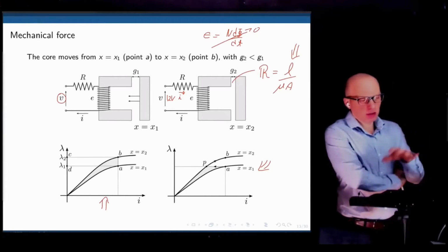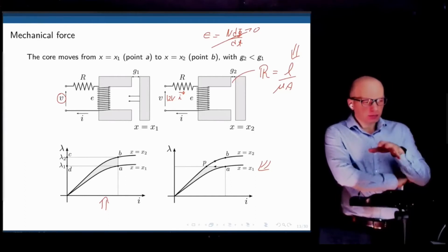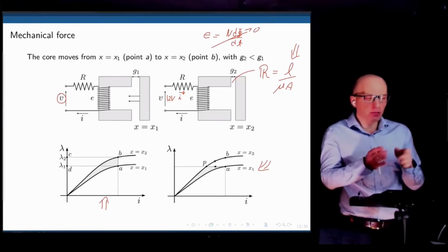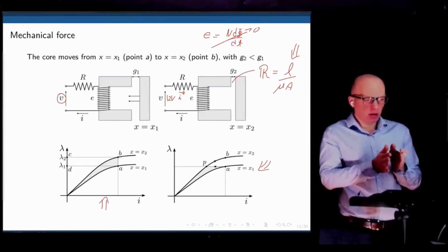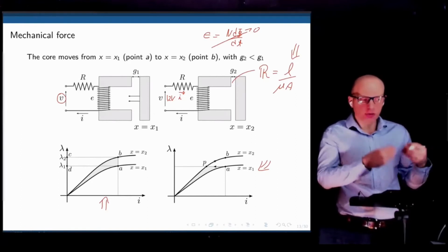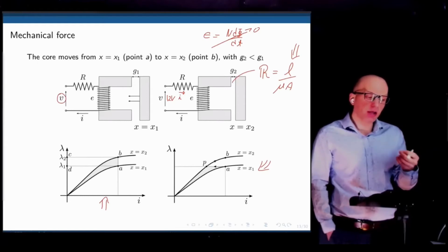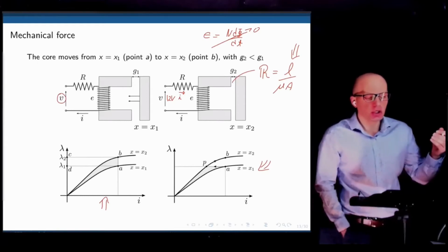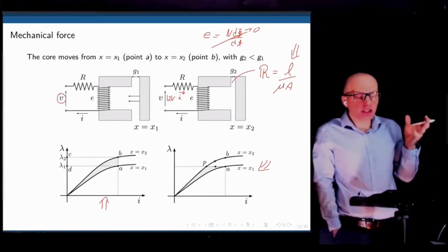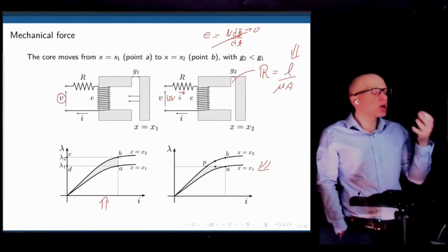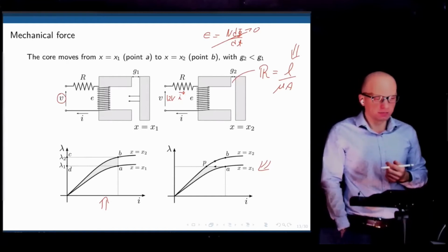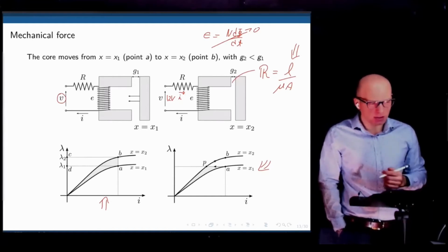to simplify the calculations later that it changes, but it's insignificant, it's negligible. And if it's very small, then d phi dt, phi changes, but d phi dt doesn't change enough to create a change in the current. But you are right, mathematically this is an assumption, because mathematically it has to change so long as there is motion, right? So long as the speed is non-zero. But if it's small enough, then we can make the assumption that if the current now remains constant, then something else needs to change in this lambda I curve, and that will be the flux linkage. Right? So that would be the second scenario.